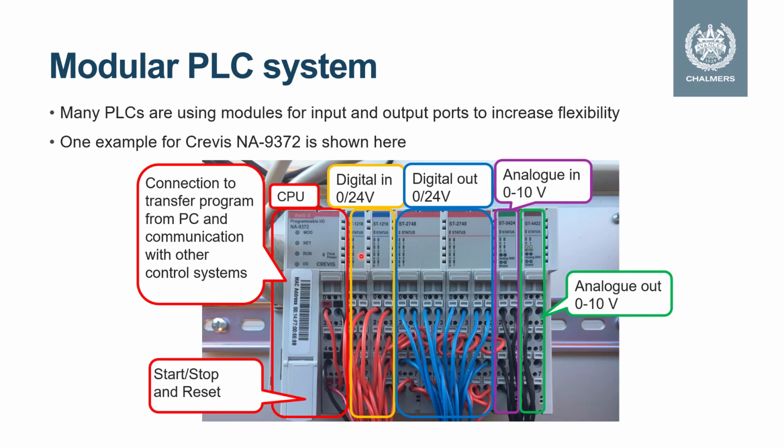The digital input signals are coming from the system into the PLC system. The system, in our case, is the elevator, which means that the digital input signals are coming from the elevator to the PLC system. The digital output signals are sent from the PLC system to the elevator. For the elevator, we don't need the analog input and output modules.